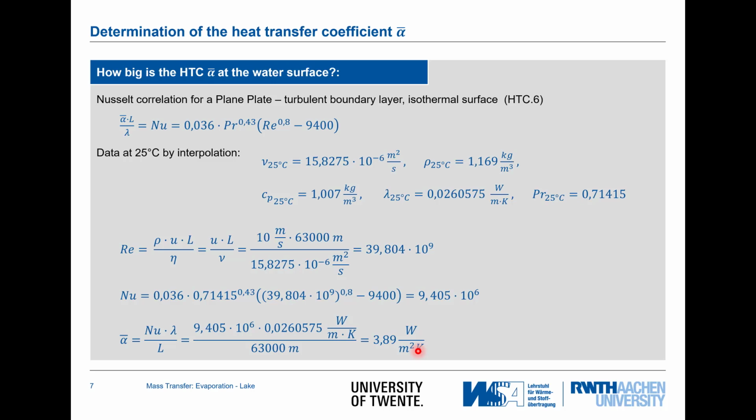And remember back at the conduction lecture videos, there we said that for natural convection we have single digit to maximum 20 watts per meter squared in Kelvin for the heat transfer coefficient. So this fits well within this envelope. It seems like it's a good pick.